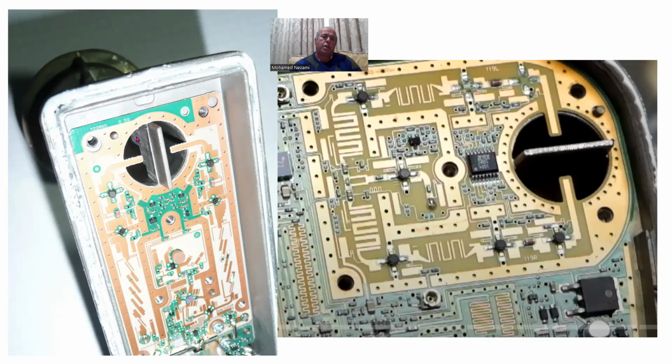There's a cap that comes in and covers this opening, leaving a little arc in here for this polarization and this polarization. And of course, these are for SATCOM entertainment TV low noise blocks. So what this is doing, really, is picking the horizontal and vertical of your favorite program.